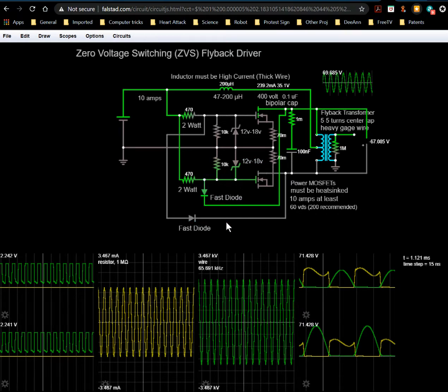They're allowed to conduct, and when they conduct, a transistor is kept off instead of on, like you might expect. Okay, but then it's alternately blocked, and when it's blocked, the transistor turns on because this voltage is not short-circuited across this resistor. So it just goes back and forth and back and forth, and that's where you get this action, whose frequency depends on the value of this capacitance and the value of this inductance. So anyway, that's pretty much it in a very long nutshell.